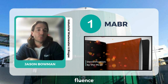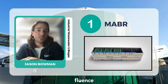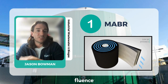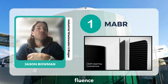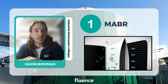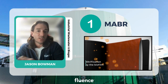So this creates a perfect condition for autotrophic bacteria, i.e. nitrifying organisms, to develop on the membrane surface, and we refer to this as a biofilm. This occurs, number one, because autotrophic bacteria love protected surfaces and static surfaces, and number two, they require a high oxygen gradient to promote growth and ammonia reduction. For those of you who know anything about biofilm-based systems, they can be highly robust and provide added stability because essentially the bacteria always remain fixed within the reactor, and they tend to self-regulate.